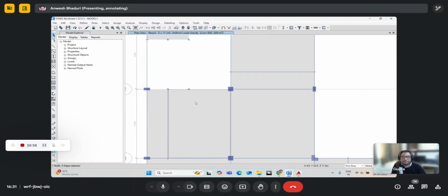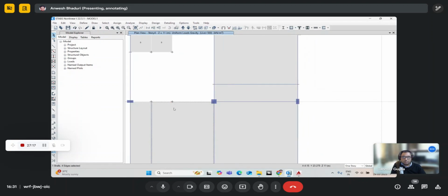If you model any horizontal floor as a thin shell, the bending property of the shell object gets turned on. So whatever moments or shears are being generated will get transferred here and even at the junction. But you will have to make these joints over here.